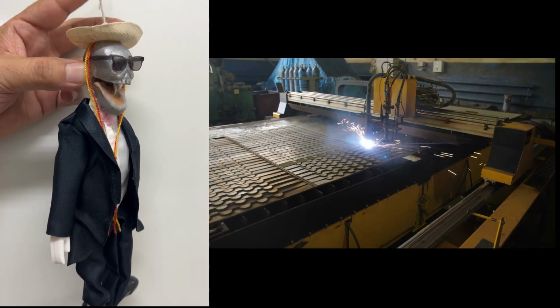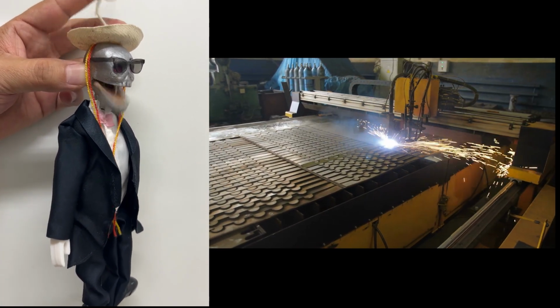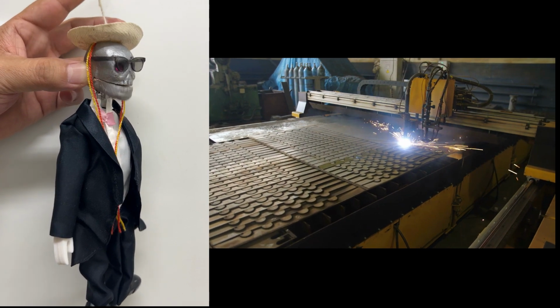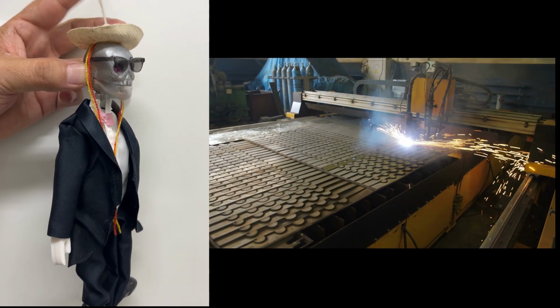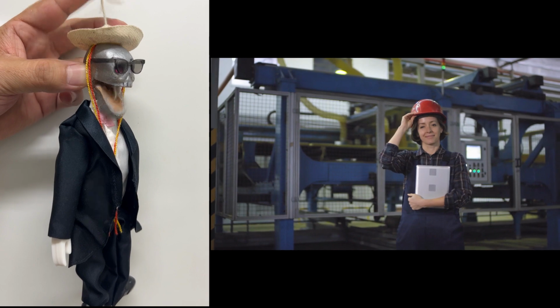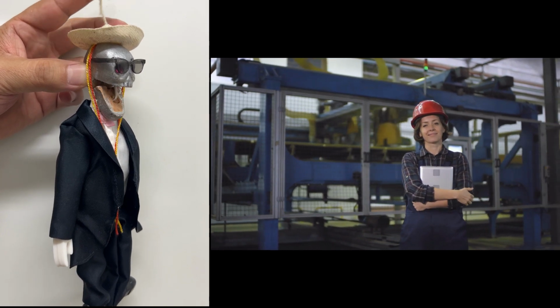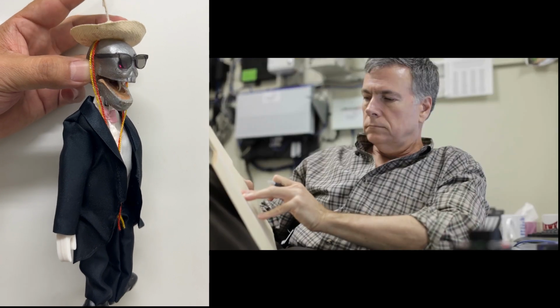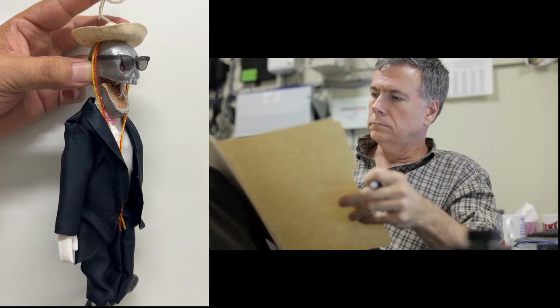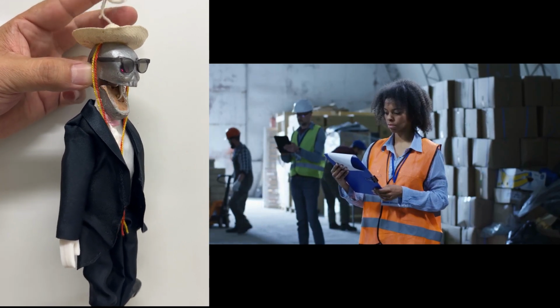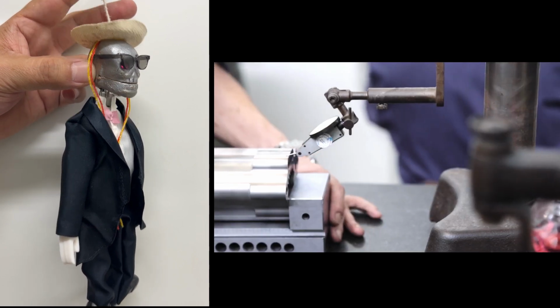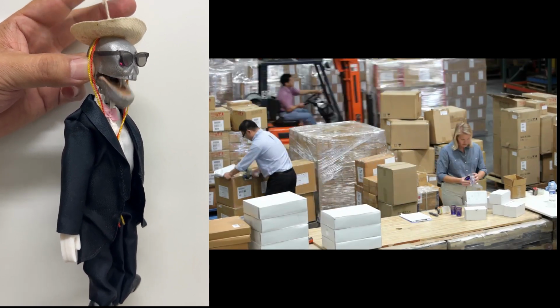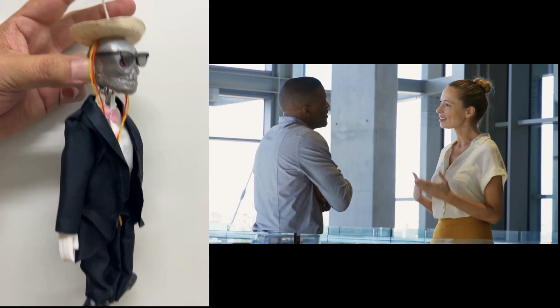Go to the machine and watch it running. It is also a good idea to take videos so you can analyze them later. Talk with the machine operators. They know the problem inside and out, and they can offer good ideas and suggestions for improvement. Review the procedures and work instructions. Walk around the shop. Check the materials. Check the gauges being used. Review packing materials and talk to the personnel in other departments.